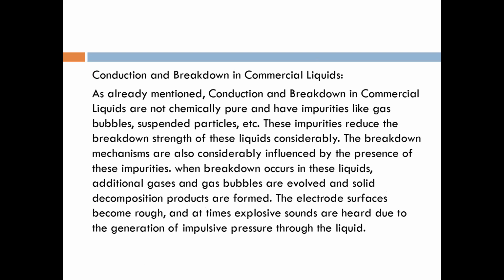Now, conduction and breakdown in commercial liquid. We have seen the pure liquid, now the commercial liquid. As already mentioned, commercial liquids are not chemically pure and have impurities like gas bubbles, as I told you, and suspended particles, just like solid particles. These impurities reduce the breakdown strength of the liquid considerably. Always remember that the insulating property of any liquid decreases due to the content of gas bubbles and suspended solid particles.